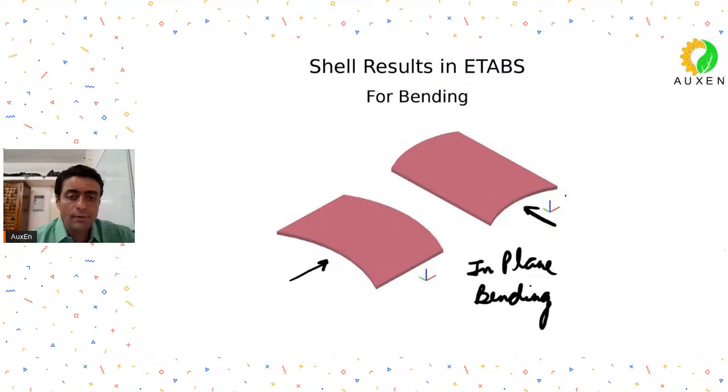Any slab panel which, what did I say, which is rigid has a very, very high in plane bending resistance. Why does it have a very high in plane bending resistance? Because it has such a large depth. I think you can imagine, for in plane bending, what will be the width and what will be the depth of this cross section if you wanted to find out the moment resistance, isn't it? So it has a very, very high in plane bending resistance in rigid diaphragms.